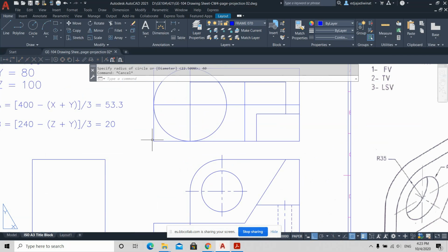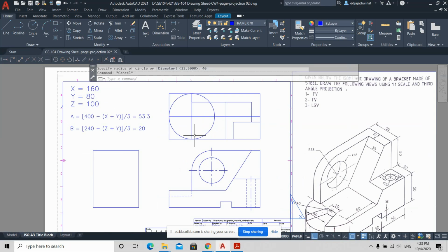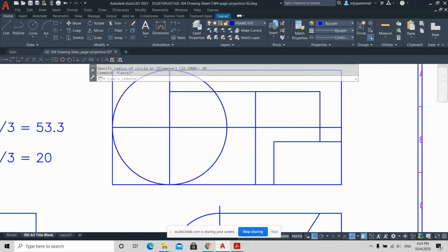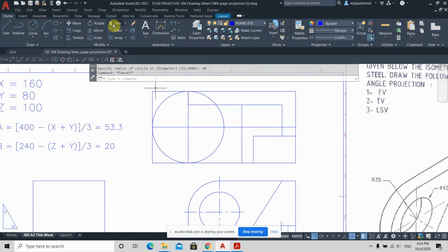Of course, you can use the helping line. Make a line 40, comma 40 to reach this point, and then you make a circle. Both are acceptable. And then if you feel this is too crowded, you can trim the lines that you don't need. You don't need these at all. That thing, this one, I will just delete the whole thing, because I will use the delete command, not trim. Delete. And what else? I'll keep this for the center line as usual. And I'll trim this. There.